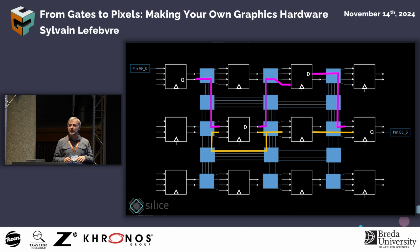One interesting thing to look at when you look at a route like that in the FPGA is the critical path. This is the slowest route through the combinational cells of the FPGA. So the Q output here is a flip-flop at the top left. And the D outputs are the combinational output of the lookup table. So they update as quickly as they can. And you can see that the last pin over there is also on the output of a flip-flop.